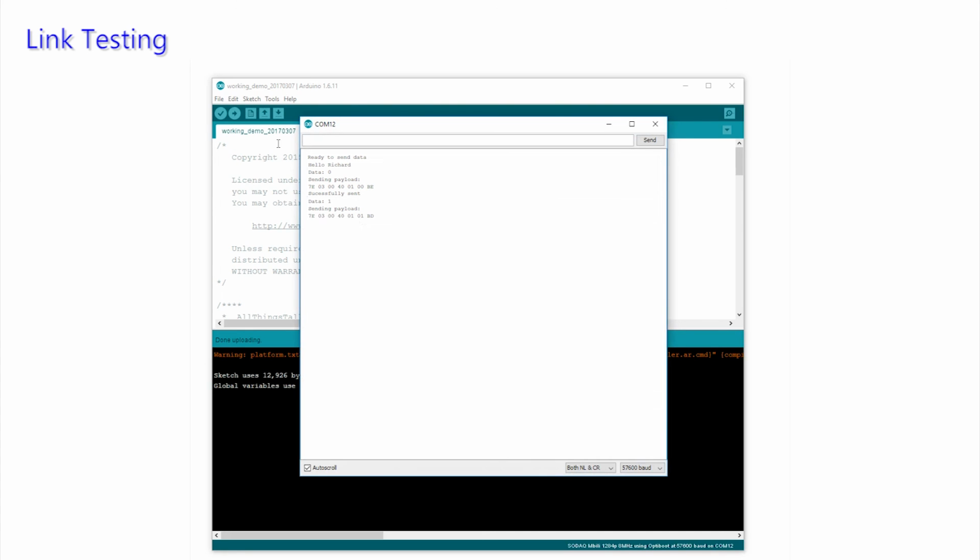Pressing the button too rapidly introduces the first experience of how IoT is designed for low bandwidth traffic. Back comes the response. Maybe the last couple of packages were sent too quickly after each other. Minimum of 15 seconds recommended. There is a limit to how much data may be transmitted, and we have hit it here.